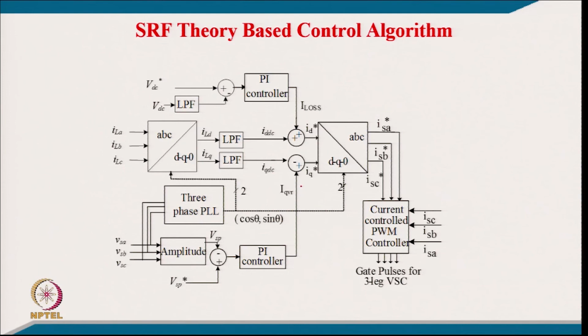and we control the voltage, again using a PI controller. So, this is to be generated by the D STATCOM minus the reactive power required by the load, which it meets locally. The difference will flow into the supply, and we have ID and IQ of the supply, and then we use the DQ to ABC transformation. So, we get the 3-phase reference current on the grid side, and we sense the grid current, and we have a current controller to generate the gating signals for the 3-phase voltage source converter operating as the D STATCOM. So, that is the block of the synchronous reference frame theory.